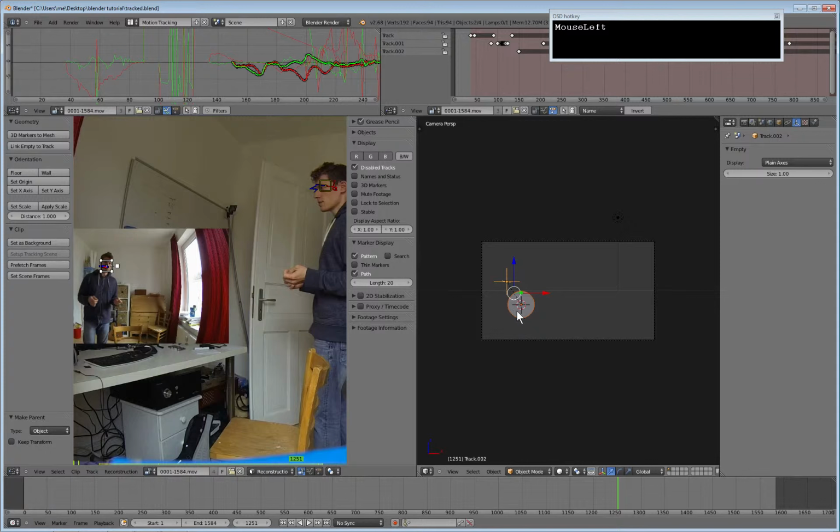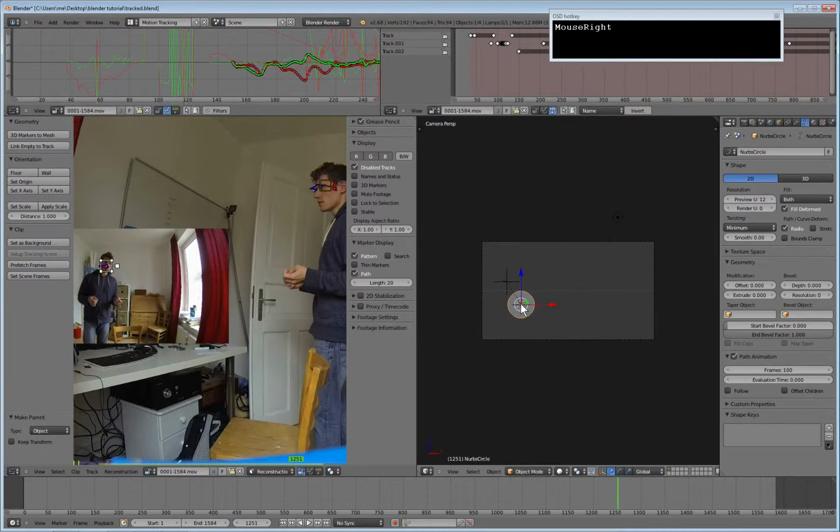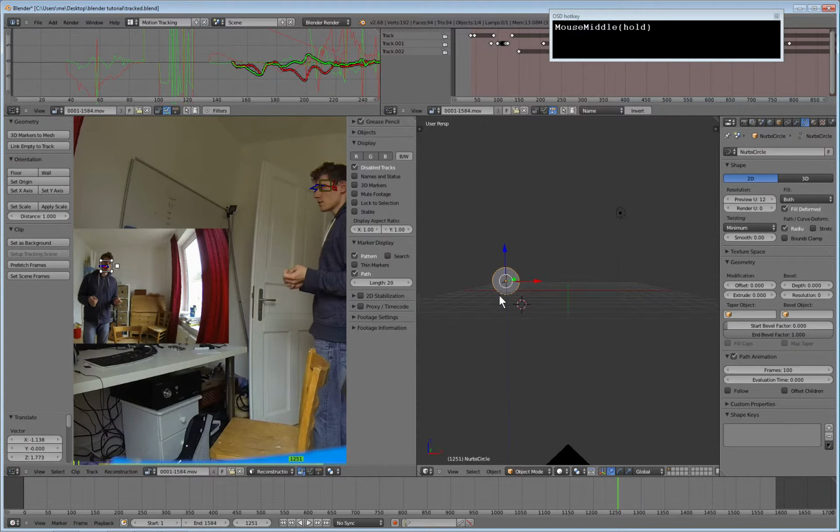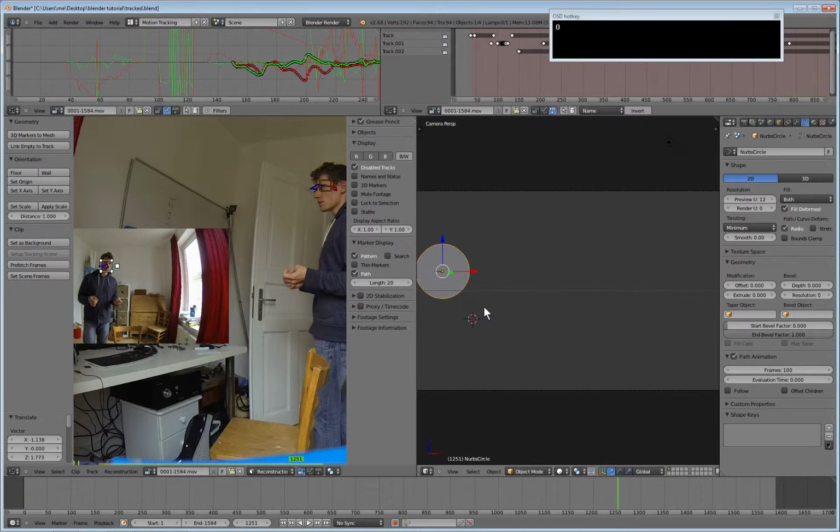And then by selecting the object and grabbing it with G and placing it on the parent object, we can align them so that the disk follows the coordinates of the path. And if I take the middle mouse and check the scene, I see they are perfectly aligned. And that's because I had the camera angle and aligned them according to the orientation of the camera, I guess.